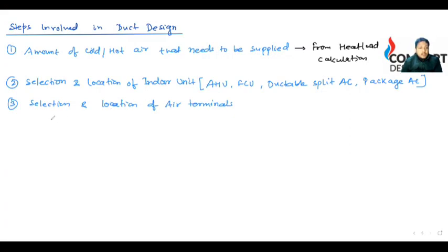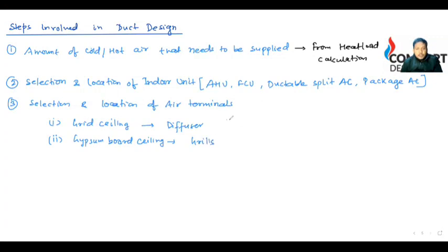Selection location of air terminal. A few options are there: where there is grid ceiling, here diffuser is preferred, and where there is gypsum board ceiling, there grills will be preferred. So this is your preference.